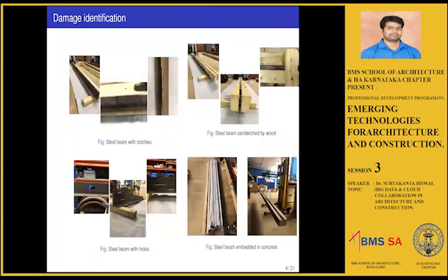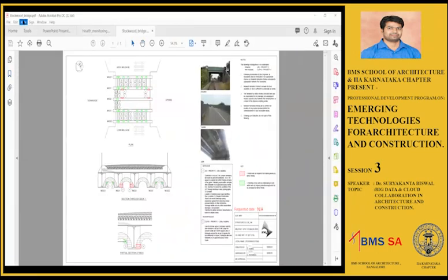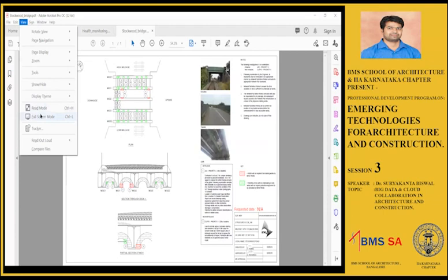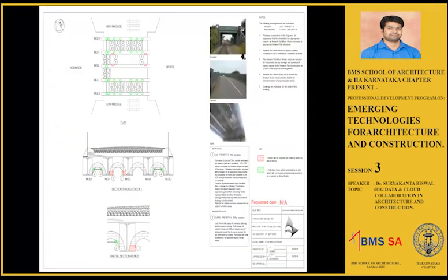So next is a case study for this one. This bridge, I think, is a Stockwood bridge. These are called jack arch bridges. In these kinds of bridges you have steel girders, but the steel girder is sandwiched with jack arches, which are masonry arches. The purpose is to prevent the exposure of the metal to water, so that there won't be any corrosion. But there was a big accident in 2009 in Scotland.